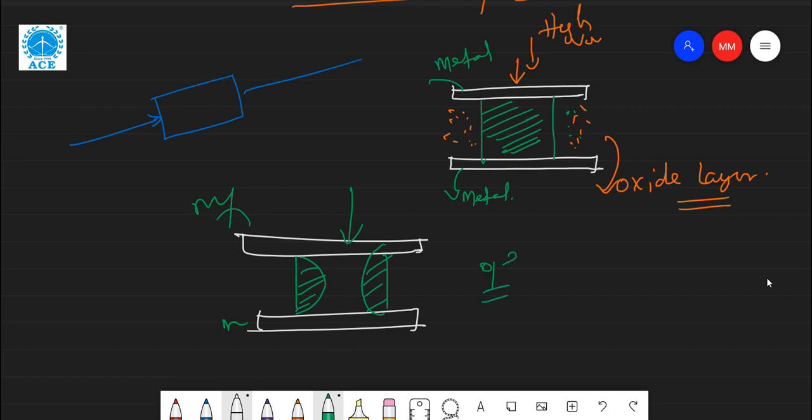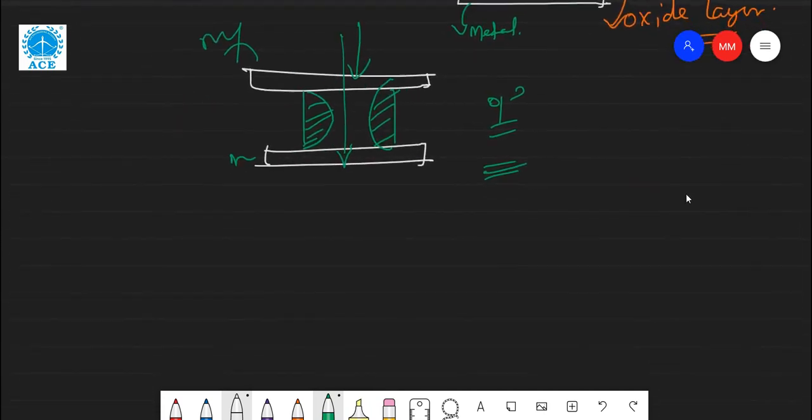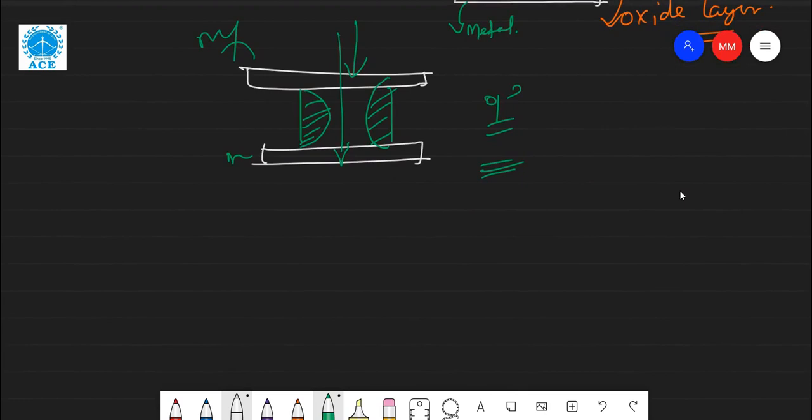When unprogrammed, these paths have a high resistance value. So if you program this one, it starts conducting, and this becomes a path. This is one of the basic examples of antifuse. Remember, antifuse technology is a one-time programming technology. Once you write it, it cannot be taken back. So this is fixed, you can say.